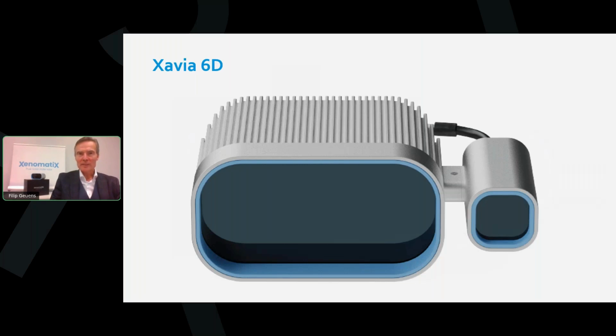And although we invented this type of solid state LiDAR, we do not consider camera to be the enemy. No, on the contrary, we're big fans of sensor fusion and of the combination LiDAR camera. That's why we have created this combo. The 2 are in the same housing, they're fully synchronized, they're upfront aligned, and they are close to each other. As a result, there is only a small parallax error and there's almost no occlusion. And so LiDAR and camera see the same thing.